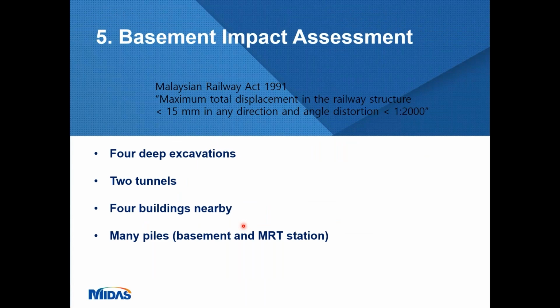This is a third example. Our client was desirous to redevelop an existing shopping complex. The redevelopment is located within the second reserve of an underground MRT station. According to the local Railway Act, the basement has to be designed in such a way that it will not cause excessive movement to the MRT structures. The maximum permissible induced movement of the MRT structure is only 15 mm.